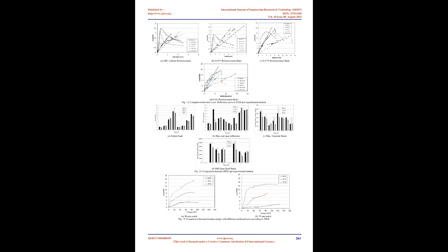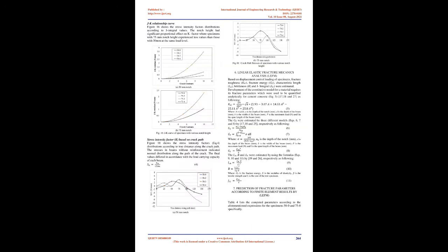Parameters needed to define the material models were element, meshing and boundary conditions. An 8-node linear brick, reduced integration, hourglass control element was used to model the concrete as shown in Fig 4. A 2-node linear 3D line element was used to model the steel bars and stirrups. This element transmits only axial load. Numerical trials were used to select the ideal mesh size using different mesh sizes. A fine mesh consisting of elements with maximum area of 1 square centimeter is used because a finer mesh does not show significant differences in results.